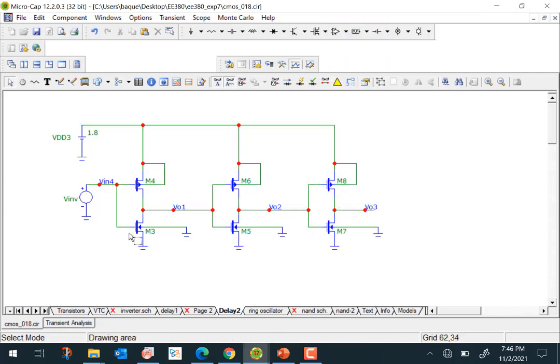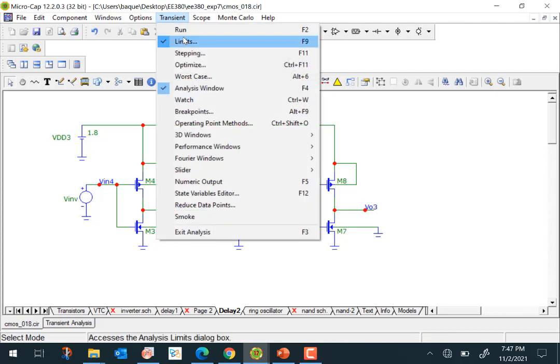which is another inverter. And compared to these two, here we are applying an abrupt input, and normally the inputs applied to a gate will not be abrupt. They would be coming from some other gates, right? So in that sense, the most realistic delay value is of this middle inverter, because the input is gradually varying and it also has a load. So what you can do is simulate these three inverters in series, connected like this, and measure the delay of this inverter, this one and this one, and see the waveforms and study them.